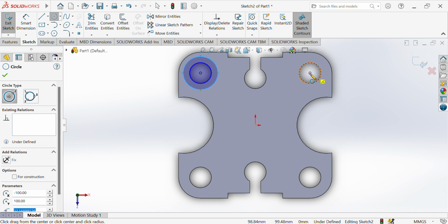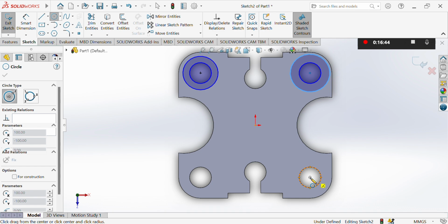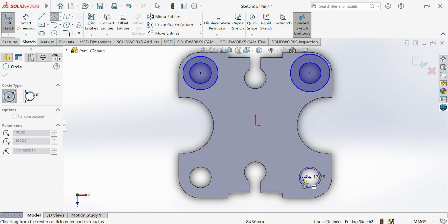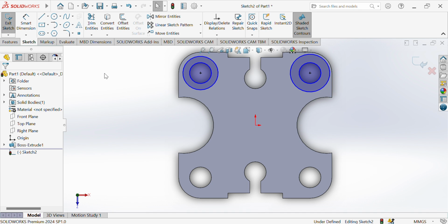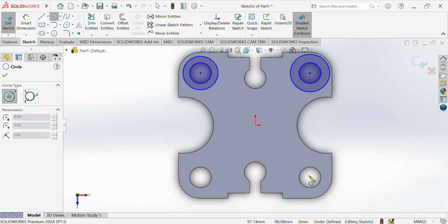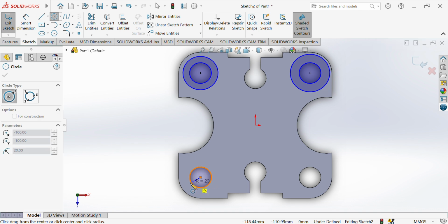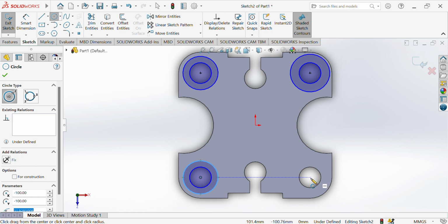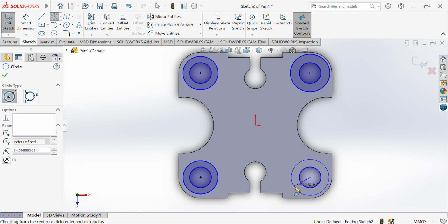Okay, let me try and find that center point. When you're drawing the circle, you can just check for the center point. It makes it easier. Escape. Let me do that again. So you're just drawing those circles out. Okay, that's basically going to extrude cylinders.